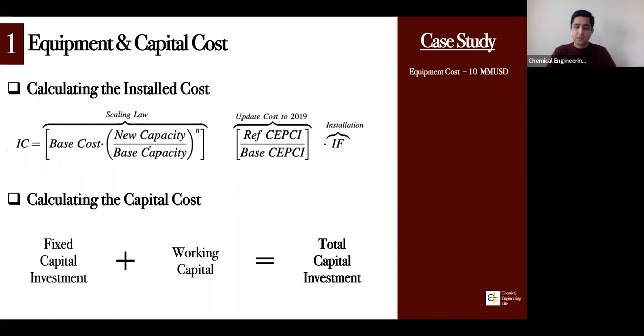Then what you do is you go in and scout the literature, and you find the cost for a given capacity within a book or a literature study. Many times it's good to always use validated papers, papers that have been written by maybe the government or different universities. Let's say you find from a paper that 10 cubic meters capacity of a flash tank costs $5.